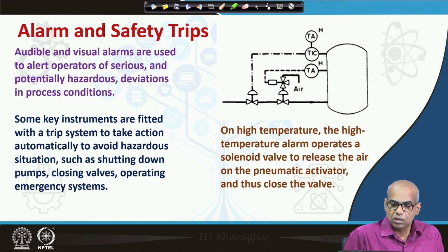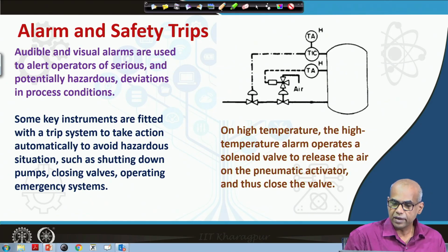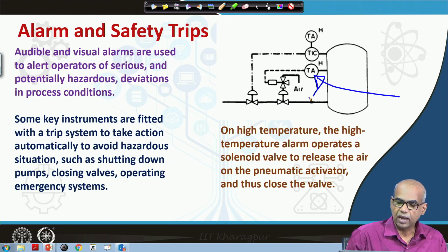The figure shows that on high temperature, the high temperature alarm will operate a solenoid valve to release the air on the pneumatic actuator and thus close the valve.